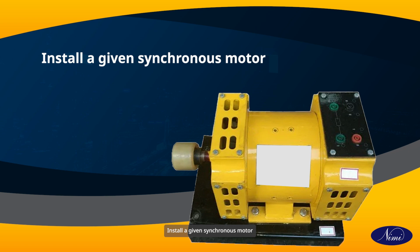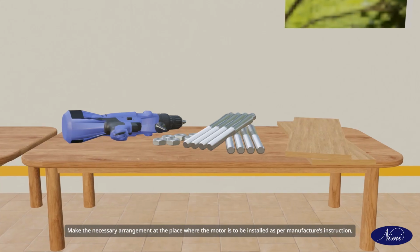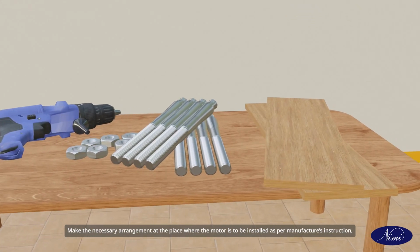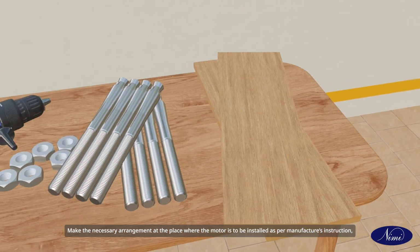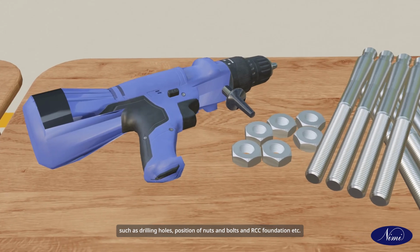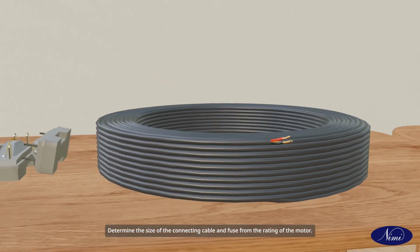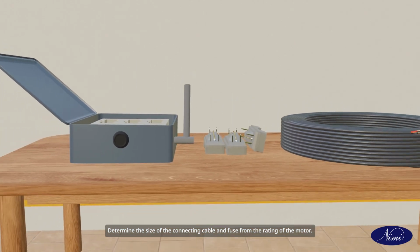Install a given synchronous motor. Read the nameplate details and record in the motor maintenance card. Make the necessary arrangement at the place where the motor is to be installed as per manufacturer's instruction, such as drilling holes, position of nuts and bolts, and RCC foundation, etc. Determine the size of the connecting cable and fuse from the rating of the motor.